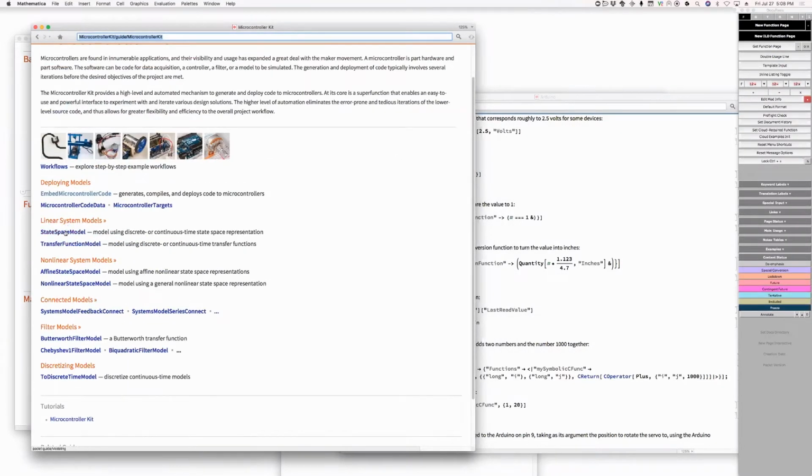Okay, so we've got these various system models, which you tell me are essentially these differential equations that turn into difference equations. Yeah, and when you hear us talking about that in signal processing and control, we say it's a continuous time model or a discrete time model. Continuous time means differential equations. Discrete time means difference equations. Okay, so that's the discretization. Yes.